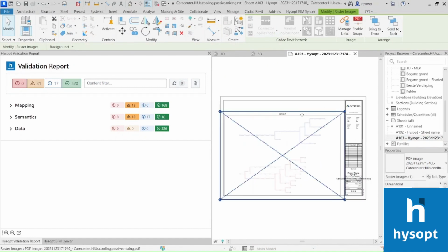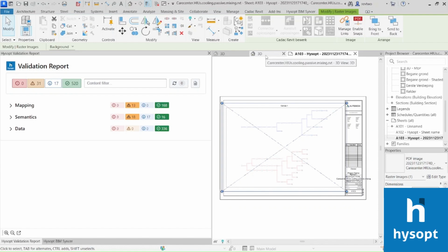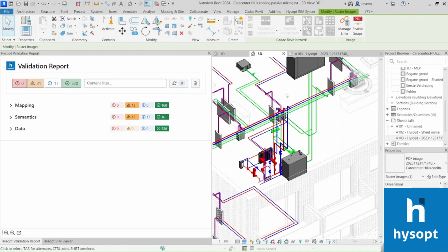Okay, so this was our first demonstration. We started from an existing BIM model that had not yet been fully calculated correctly, and we were also uncertain whether it still contained hydraulic errors. We then used the generate function to generate a Hysopt model where we could easily see that some pumps were missing. And then we did our design calculations correctly by taking regime changes and concurrency into account. And lastly, we carried out the pipe selections according to the standard and synchronized that back to our BIM model. And all of that in a span of a good 10 minutes.